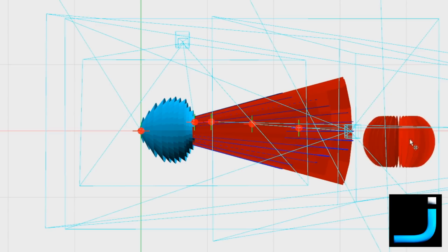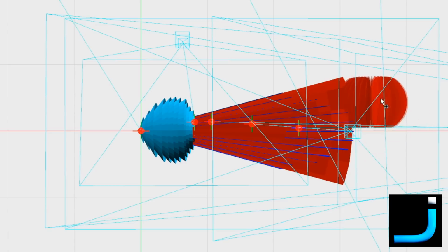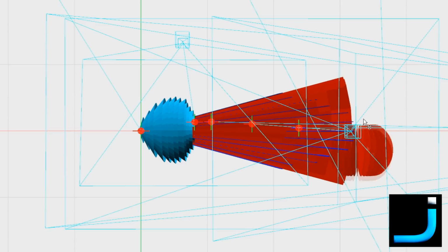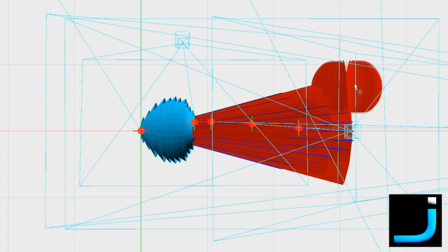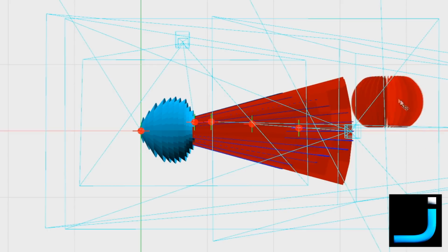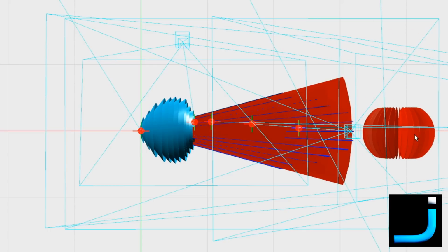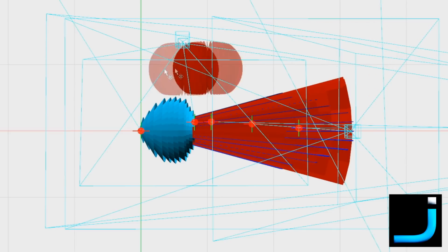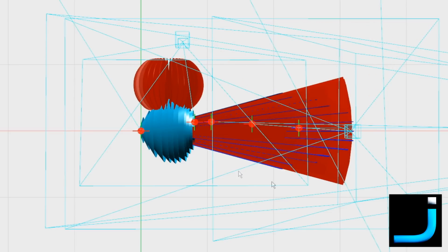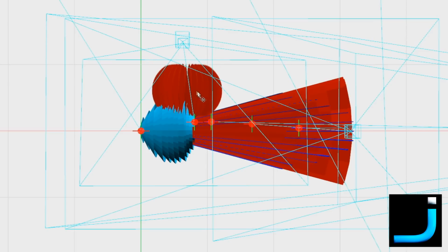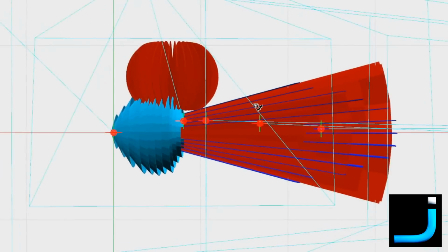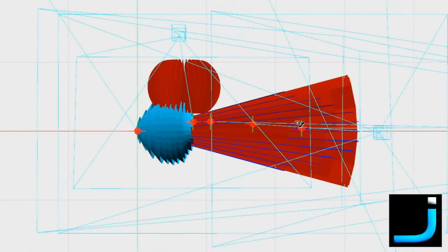And that, I feel, would give you probably the best all-round performance, because you've got that long range on the antenna tracker with your Yagis. So wherever you are in the sky, the antenna's going to follow you. And again, when you come into land, even if you happen to be out of the field of view of the Yagis for a moment, the circular antenna is always going to be giving you maximum reception.